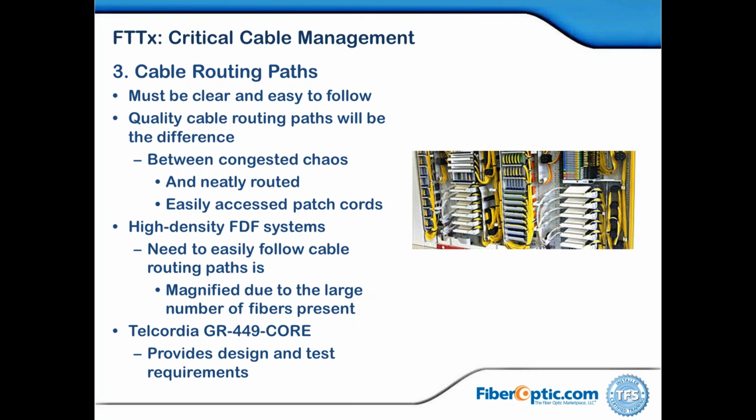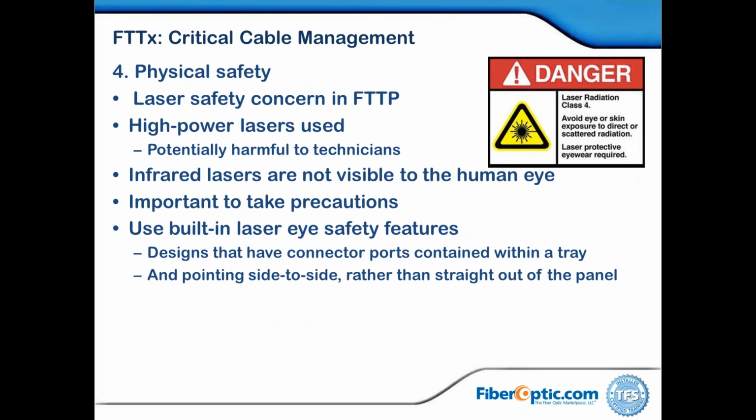Most components are available up front with easy access. So that's how you manage it. The other is physical safety concerns. Since there are high-powered lasers from the central office, they can be harmful to technicians. And since they're not visible to the eye, you must take precautions, like built-in laser eye safety fixtures. So they can be designed with the connector ports contained within a tray, or with connector ports which are angled out or fold out so that at any given time they're not within the line of sight of a technician working on them. And that's what I mean by the point-to-point.